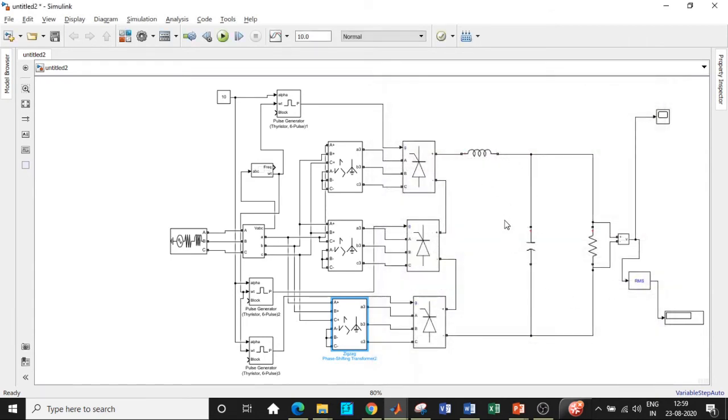So we have entered all the parameters with respect to our circuit, I believe. So we can simulate them and look at how the waveform looks like. So I am not going to give a huge simulation time. I'm going to give it 0.5 or 0.3, not more than 1 or 1.5, because the synchronization block takes a lot of time to simulate according to our supply frequency. So that's the reason. So now I'll be clicking on run.